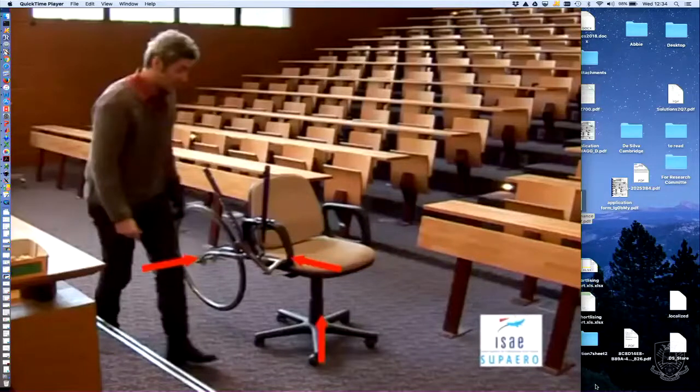So the example I gave you about the bike is that you're changing stuff around the moment axis and you're getting a precession. Okay, so the spin stays constant, and then you either change precession to get a moment, or you change moment to get a precession. So that's the way that you can use the gyro to your advantage.